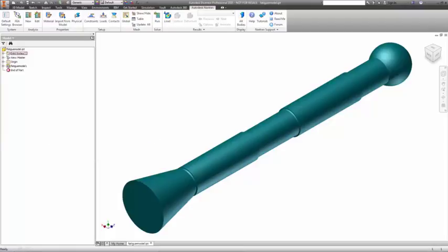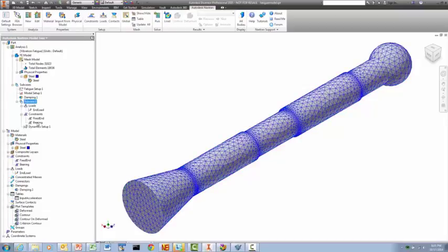Finally, it's time to run the fatigue analysis itself. The fatigue analysis takes the results of the random analysis, specifically stress levels and the pseudo-frequencies, and will generate the traditional fatigue life and number of cycles until failure. The actual lifetime is computed from the pseudo-frequencies generated in the random analysis. Vibration fatigue is slightly more complicated to set up than many other types of analyses.